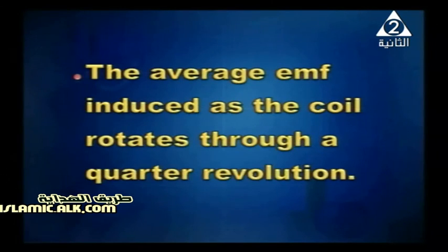Another item, we want you to calculate the average EMF induced as the coil rotates through a quarter of a cycle, quarter revolution. EMF average equals NAB or NBA times 4F. F is the frequency.